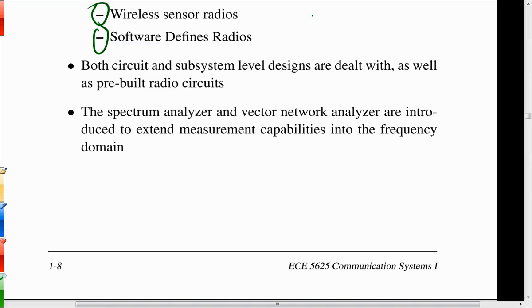Now you can be a high-speed digital designer and be caring about the spectrum because maybe there's some issues with leakage off of your substrate, and you're using a spectrum analyzer to sniff around and see what harmonics of the clock and other things are getting off your board, and your PCB design maybe needs to be modified because you've got some problems.